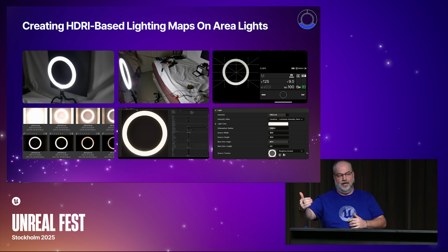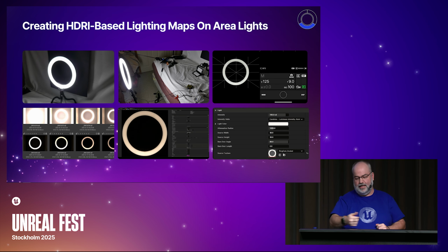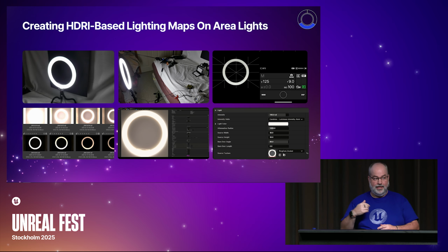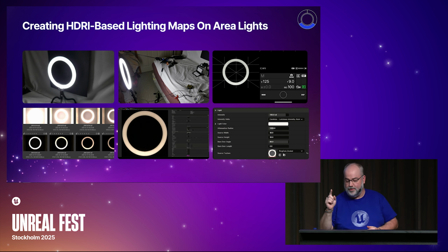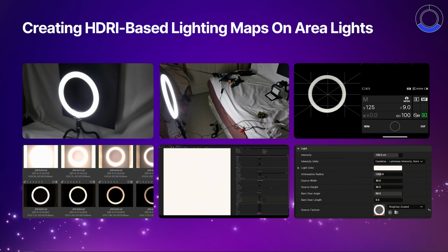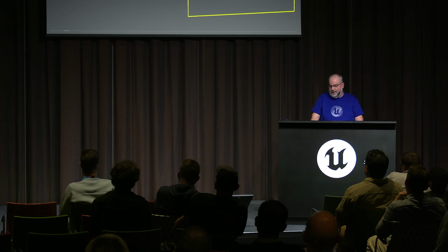You're going to shape the light with your light in Unreal with the rect light. So that's where you worry about your aspect, but your source texture doesn't have to be 8K. Like 1K is plenty, right? Just keep that in mind. But basically, you set up your light, you measure it as we talked about, you shoot your brackets, you process it the same way I showed you, and you get your HDR exposure, and you set your intensity on your light to 100 candela. The reason I'm doing that is because now I have a 100% slider that I'm going to calibrate into. It's a set value.